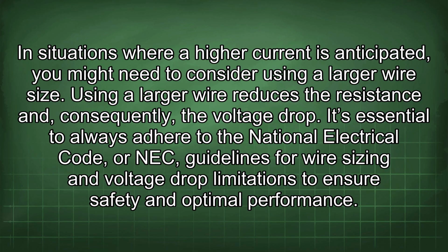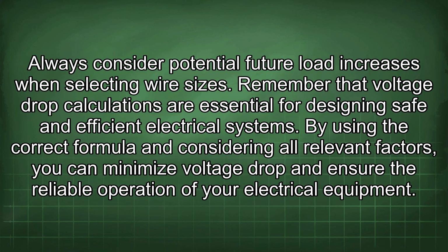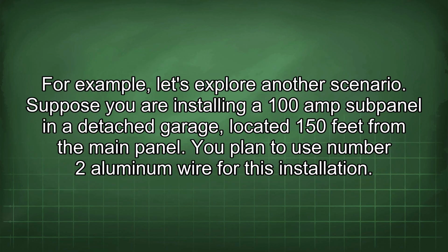It's essential to always adhere to the National Electrical Code, or NEC, guidelines for wire sizing and voltage drop limitations to ensure safety and optimal performance. Always consider potential future load increases when selecting wire sizes. Remember that voltage drop calculations are essential for designing safe and efficient electrical systems. By using the correct formula and considering all relevant factors, you can minimize voltage drop and ensure the reliable operation of your electrical equipment. For example, let's explore another scenario.